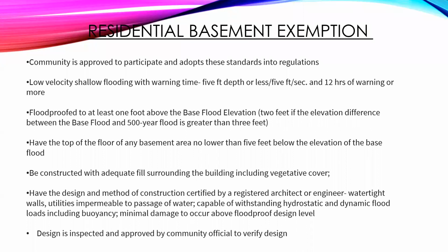And then it has to be floodproofed to at least 1 foot above the base flood elevation, the top floor of any basement no lower than 5 feet below that base flood elevation. And then it has to be surrounded by compacted engineered fill with vegetative cover to reduce erosion. And then the design is certified, that it's watertight, again, utilities, watertight, impermeable to the passage of water, and can withstand flood loads. So it is similar to the non-residential floodproofing basic requirements, but you can see how this is a bit different. We have different specific regulations on how the basement is done.